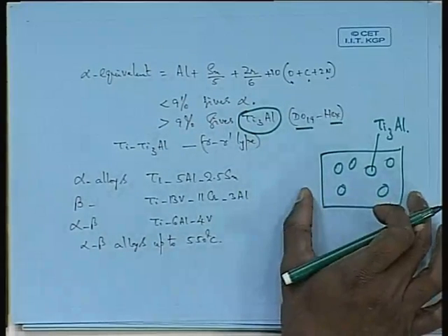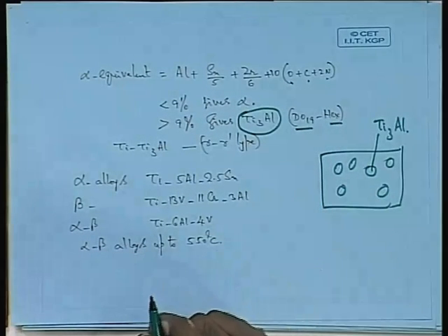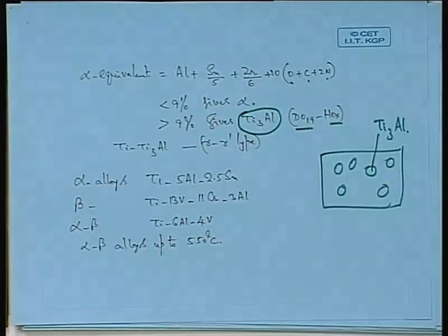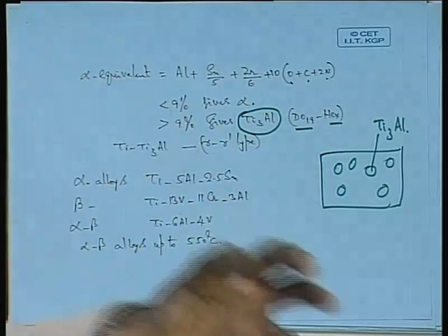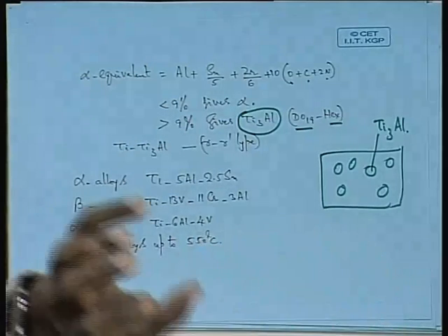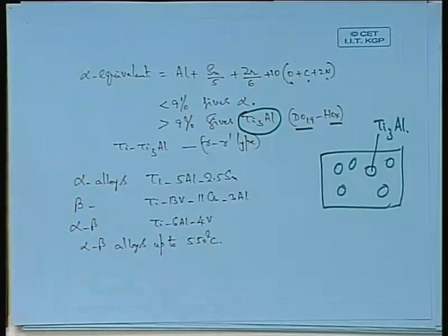And this situation is exactly similar to our nickel based superalloys, where you have gamma and gamma prime, where you have an FCC matrix which is a nickel based solid solution, and what is the precipitate there? Ni3Al. Ni3Al is an ordered FCC L12 structure, and that gives you much higher strength. And a similar microstructure we have seen in aluminum based alloys. What is that?